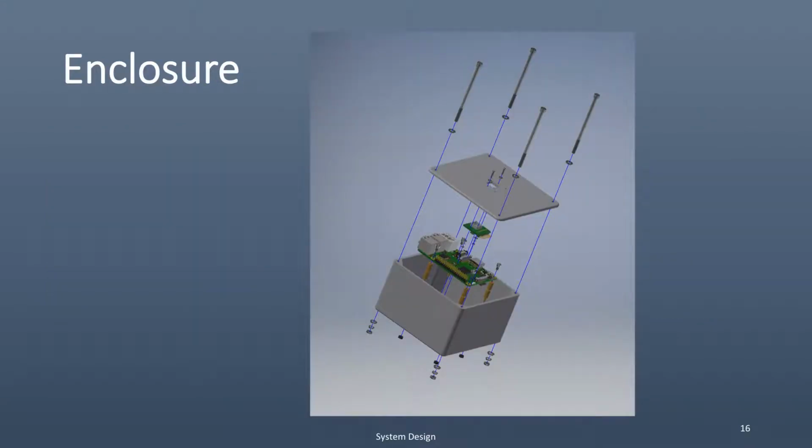For our device, I developed a 3D printed enclosure for the prototype, shown here. I also have an example that we can take a look at afterwards. It was used to encapsulate all the devices. This would definitely be an area for improvement in the future. Since the prototype's been proven out, if we were to go on further, there are many redundant components in here, such as the XBee mesh network adapter being redundant with the onboard Raspberry Pi chip, along with many ports that are unused on the Raspberry Pi.